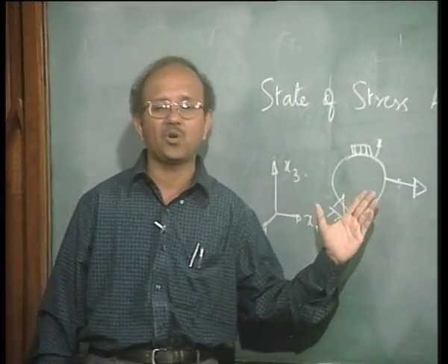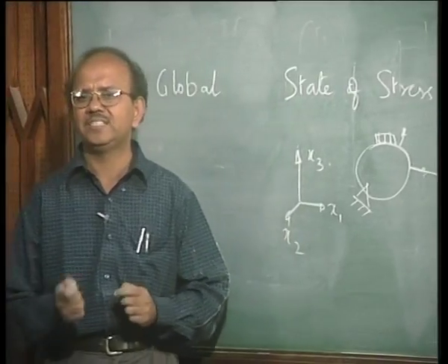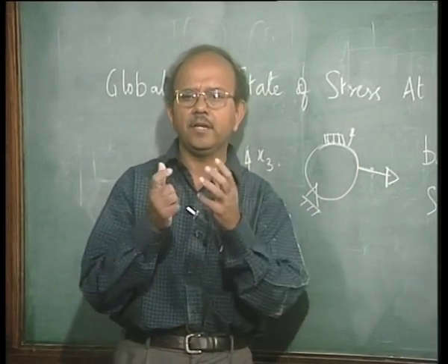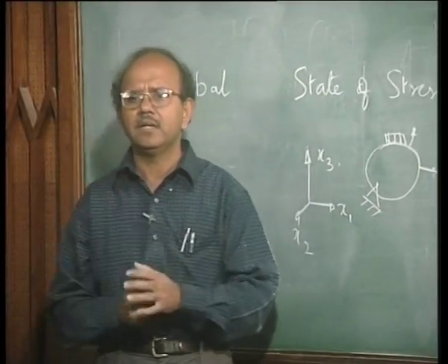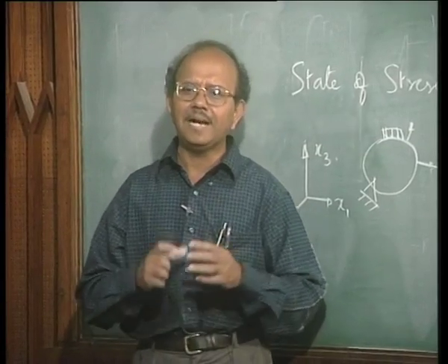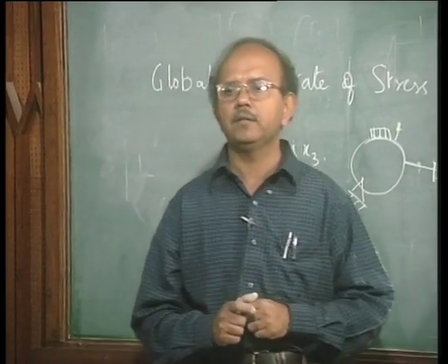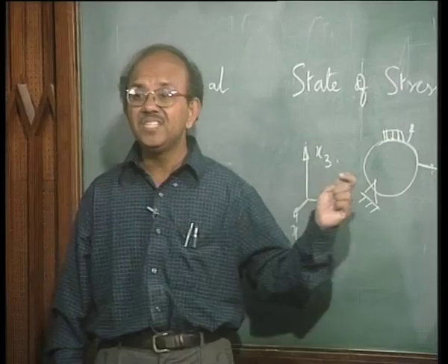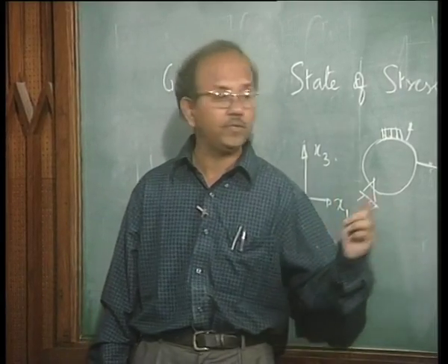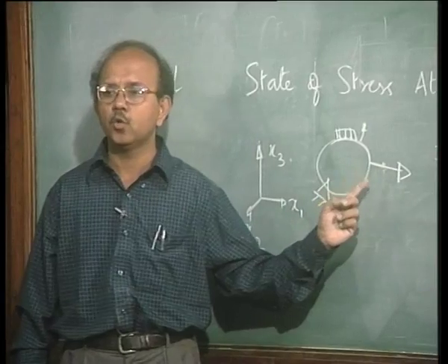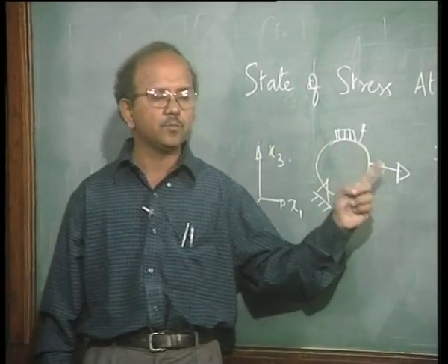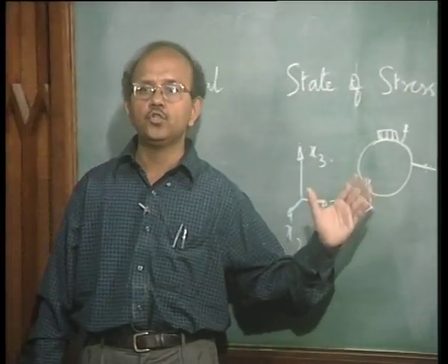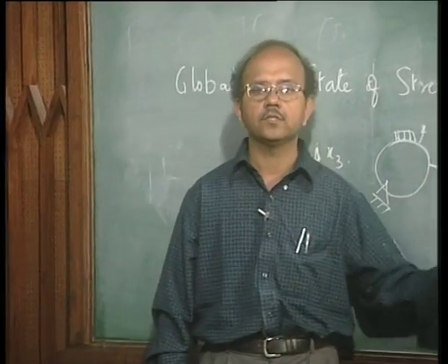In actuality, there is no such thing as a concentrated force. Forces do not act just at one point. They act on a very, very small area, an infinitesimal area, whatever it is, it acts on an area. And that has been modified to be a concentrated force for engineering purposes, and hence we have this term concentrated loads or concentrated force, and that happens to be a part of the surface force. So, stresses are produced due to this kind of forces.